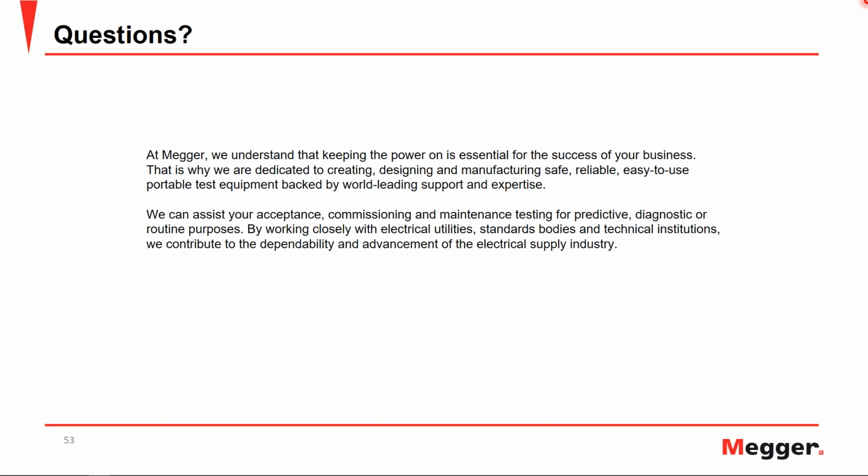To answer that question, I would go back one step. The purpose of power factor testing is to identify the condition of the insulation, and you can check the condition of insulation with different kinds of test methods. There are DC insulation tests available. High pot test is another one.